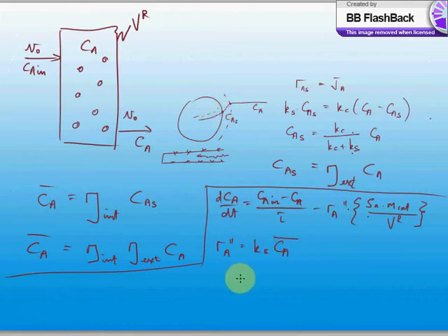So that's equal to Ks eta int times eta ext times Ca. Right, so when we replace for Ra double dashed in this equation, we now have an equation that's written just in terms of Ca. You can see here specific surface area, mass of catalyst, volume of reactor.